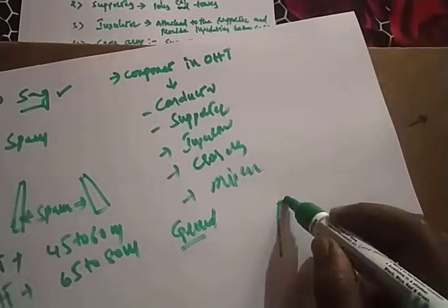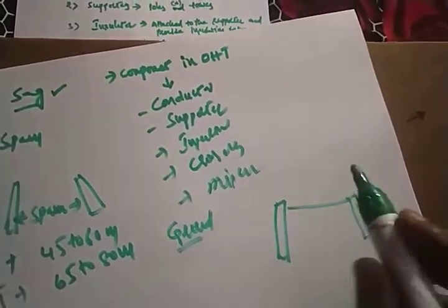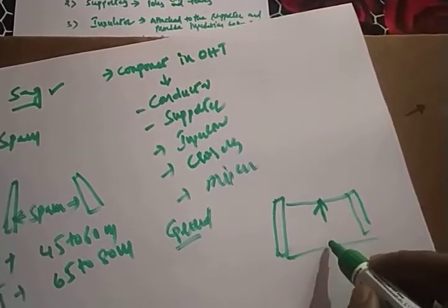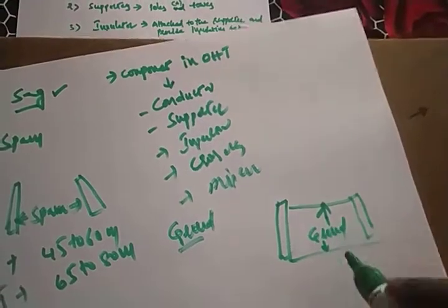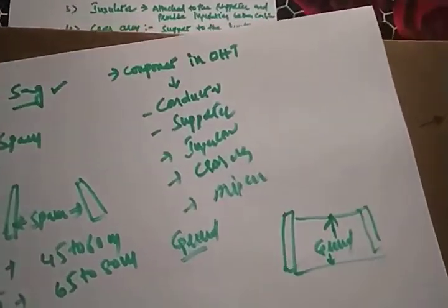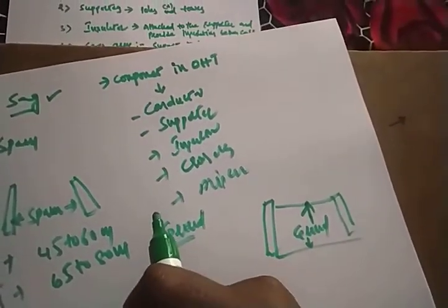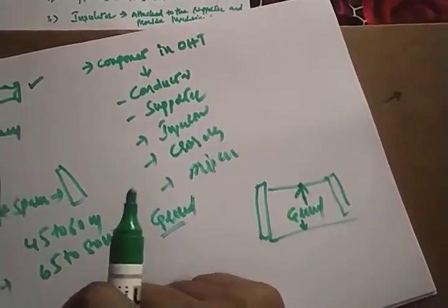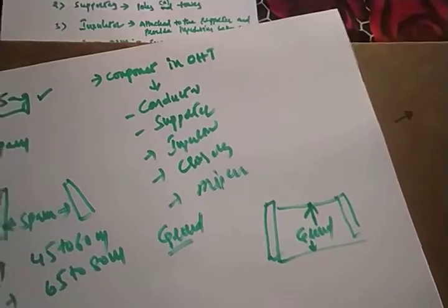So what is the ground clearance? It is the distance from the ground to the lowest point of the conductor. Suppose these are two transmission line towers, and we place the transmission line like this. The lowest point, that means the middle point, from the ground, is called ground clearance. For safety, the ground clearance must be as large as possible, whatever the system is.